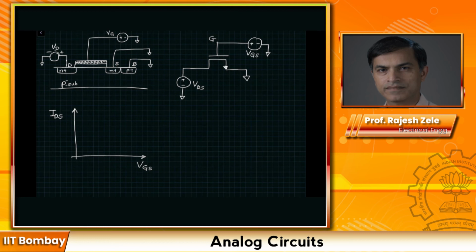So when VGS is 0 in this particular case, there is no channel formed, there is no inversion layer formed in this particular device. So we will have 0 current, IDS. There is no current flowing from drain to source. When VGS is equal to VTH, we are just beginning to form the channel under the device,